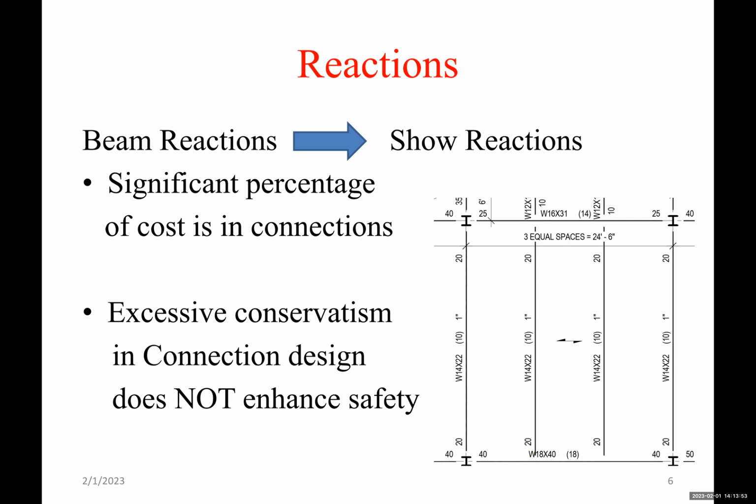So shear typically will be okay on those beams, unless of course we have a really special case where we have a high concentrated load that we have to worry about. So instead of designing for 50% of the capacity, here we have for example a W14x22.